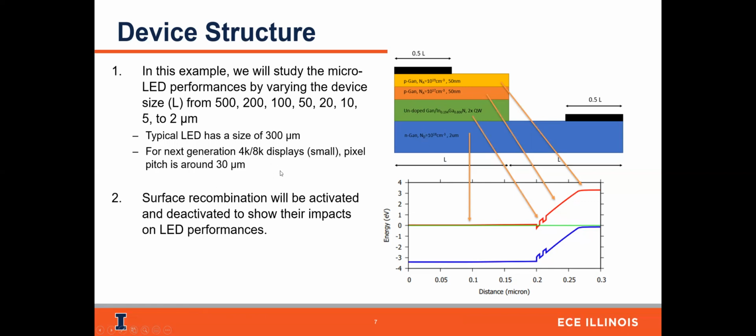So if you have more experience with gallium nitride or nitride materials, you will probably have this question: why, under flat band conditions, at equilibrium, don't I have polarization-induced sheet charges? No, because we are not including that effect in this simulation.